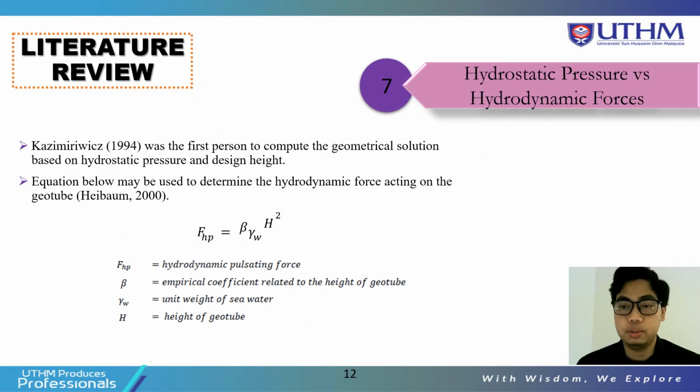Next, for hydrostatic pressure versus hydrodynamic forces. From Kazimierewicz in 1994, he is the first person to compute the geometrical solution based on hydrostatic pressure and design height. And from Hubaum in 2000, the equation below can be used to determine the hydrodynamic force acting on the geotube. So the equation below is used to calculate the hydrodynamic force acting on the geotube.